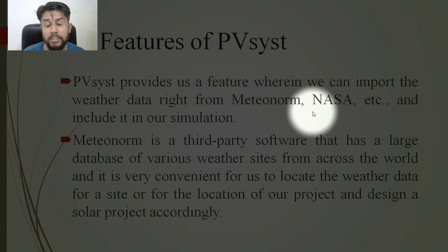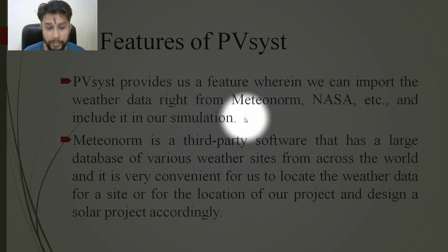Meteonorm is a third-party software. It has a wide database of weather at different locations available across the globe. So whatever location you choose, you can easily find the Meteonorm data for that location with the help of this Meteonorm data tool. So we need to incorporate this meteo data for the exact amount of generation, to make the simulation more realistic.